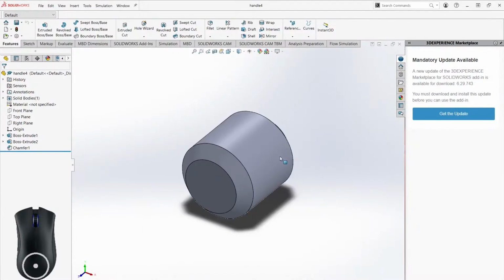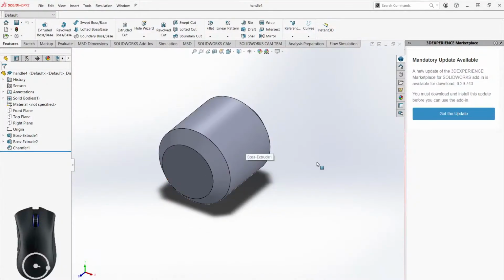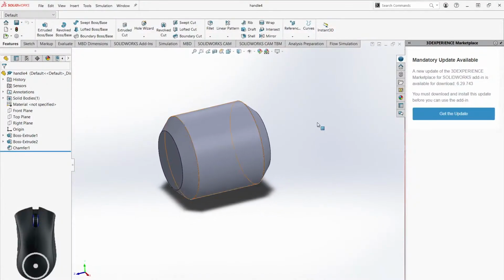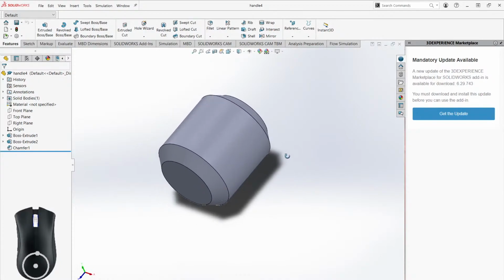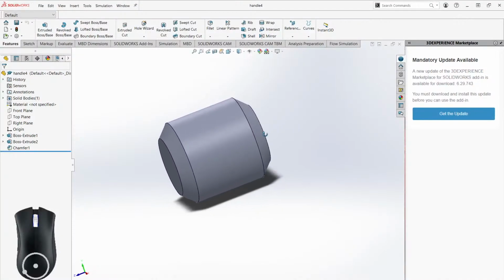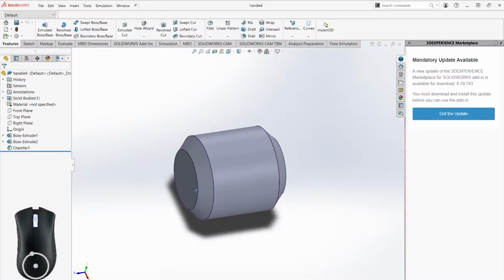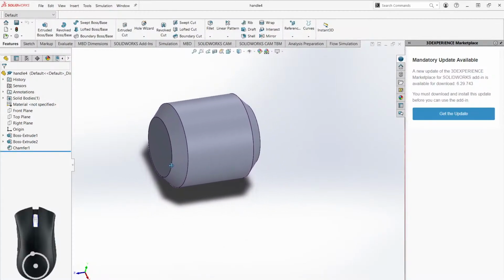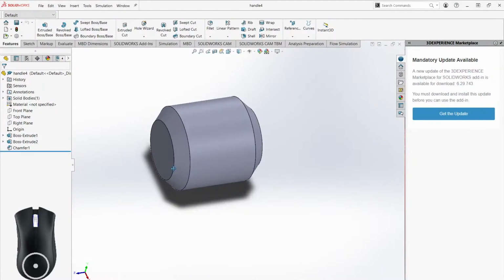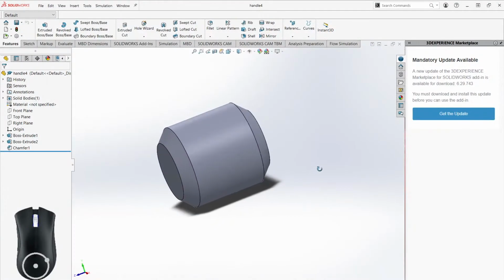So all that. And you may be wondering how I've been able to pan around or rotate like this. I'm doing that by holding down the middle mouse button to rotate. So this is me holding down the middle mouse button. It turns my cursor into the rotate icon, and I'm rotating around. And if I hold down Control and the middle mouse button, that's when I get to pan, and the cursor becomes a little moving thing, so I can move it around linearly, and this would be like rotationally.